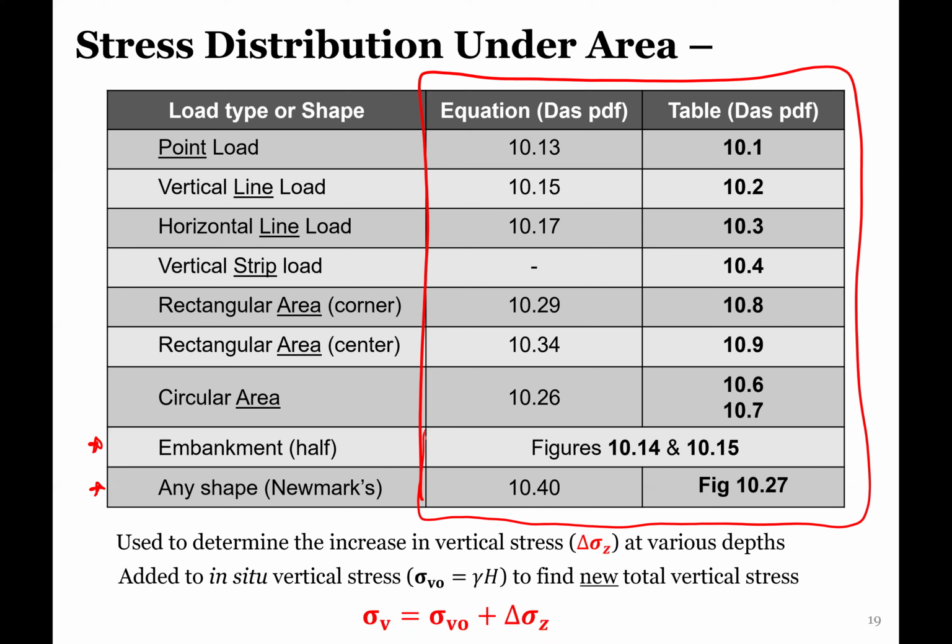And again, this is to find the increase in vertical stress. So this is due to the loading. And what we might see is that this loading can actually change over time. So we have our in situ vertical stress, and then this new increase in vertical stress might change over time due to different incremental loading. If we think about different types of construction, right, we don't just put a building on it right away. We're going to be loading it over time with this dead weight as the construction occurs.